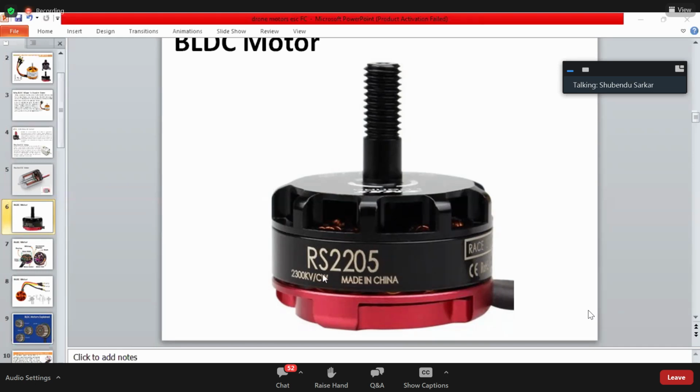So we understand the size of the rotor, we understand the mechanism of the BLDC, we understand how the BLDC works, and we understand how to get the information from the given data on the motor, that yes, this is the motor, and what should be the torque. You can find the torque in the specification chart of the motor, which says it produces that much torque, and how to match the propeller with it, meaning the wings of the drone, according to the size of the rotor stator. You have to pick your wings.